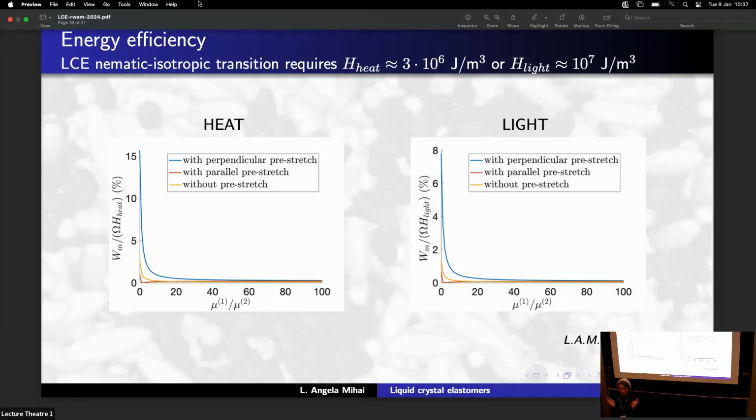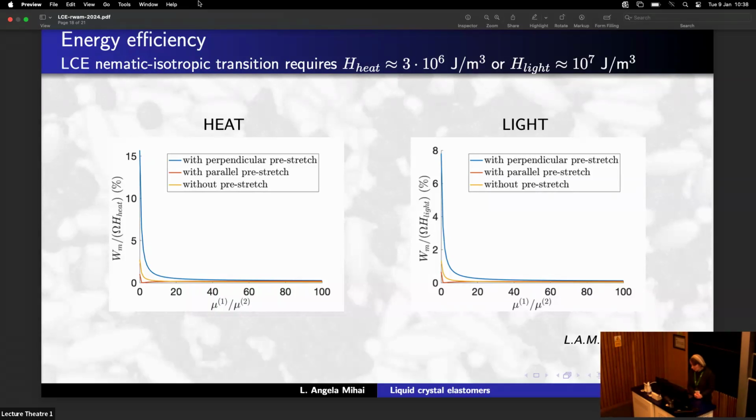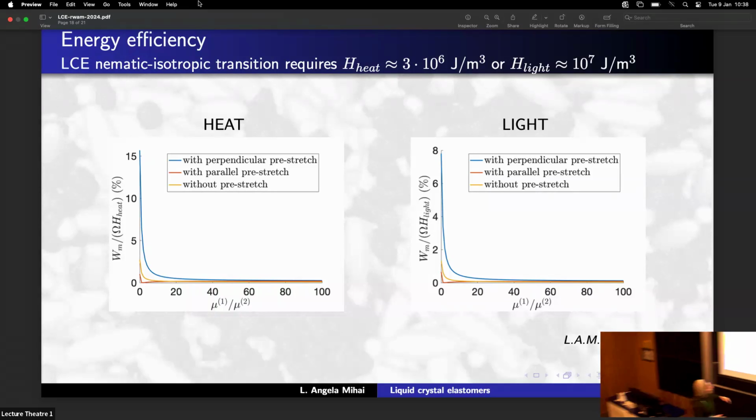So two things to bear in mind. You can just say, oh, liquid crystalline elastomers are great as dielectric, because they have this kind of instability. So you have to watch out for wrinkling, and you have to watch out for shear striping. So you kind of have to play the voltage in such a way that these instabilities are not triggered, because then the capacitor will be less efficient. But overall, for some model parameters, the performance is better.